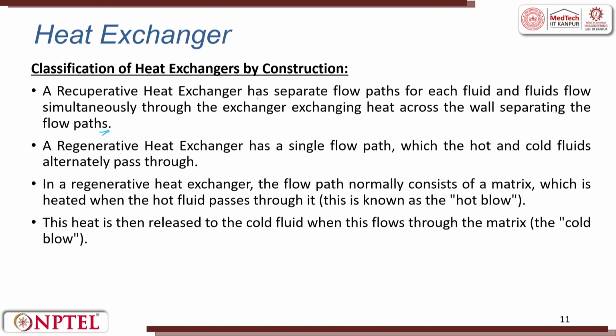So, basically it has a separate flow path for each fluid, and the fluids flow simultaneously through the heat exchanger, exchanging heat across the walls. Regenerative heat exchangers have a single flow path, which the hot and the cold fluid alternately pass through.